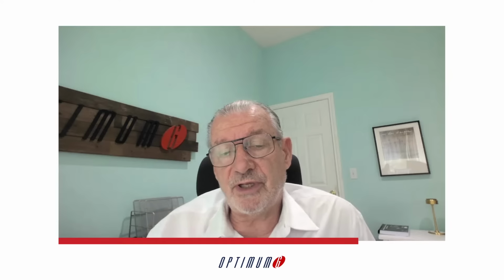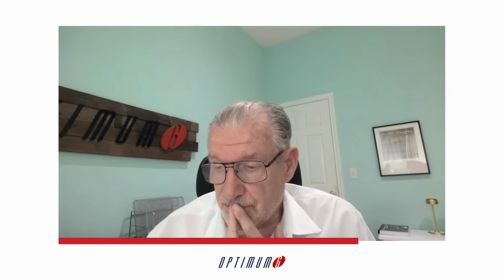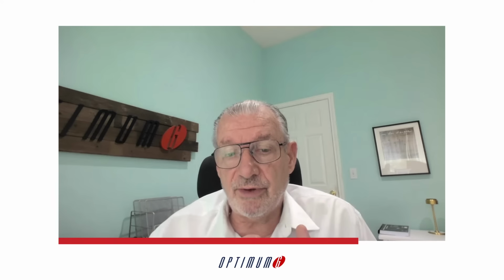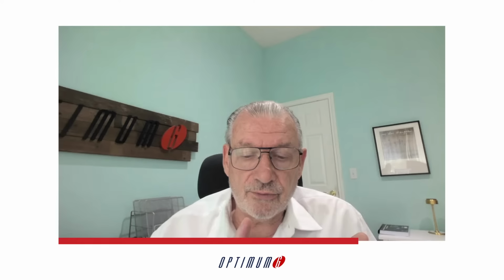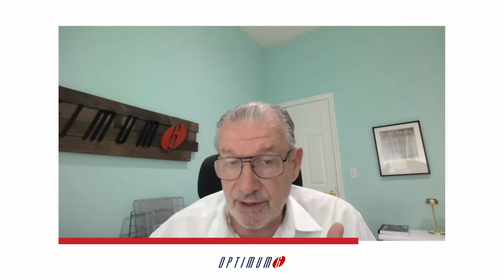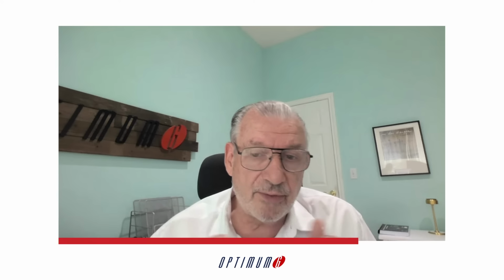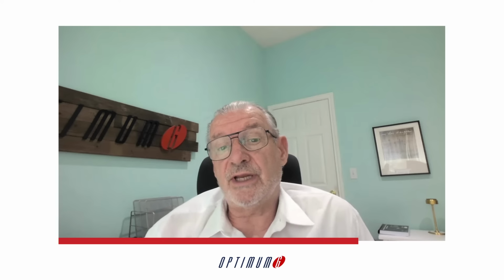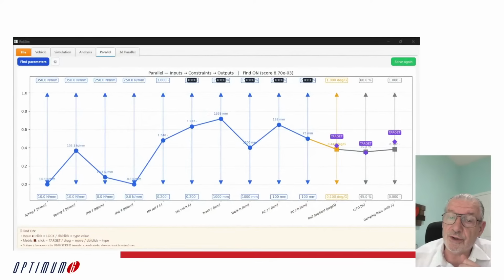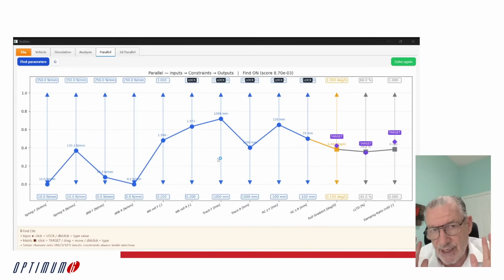And then on top of that, you can do it in 3D. In other words, I want a given lateral load transfer and a given roll stiffness that is not linear, and is changing with, for example, the roll angle or the lateral acceleration. That is very, very good, and I think people should work on this. It is bloody useful. It's very, very useful, and I think you should do that before you go to neural networks and things like that. Again, AI.